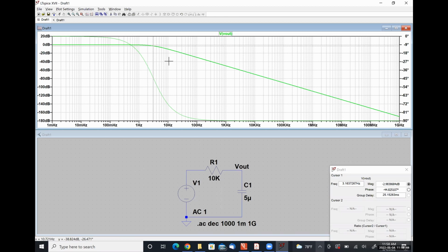So I want you to do something similar to this, except with an RLC filter circuit, where you're going to have a band pass response, and you should see that at like 89.0 megahertz, you're at -3 dB, and at 89.2 megahertz, you're at -3 dB. And at 89.1 megahertz, you're at 0 dB. If you've matched that, you're good.